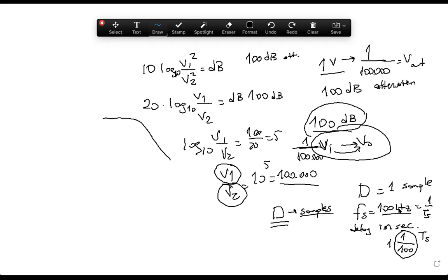That means if I give you 100 Hertz, it means 1 over 100 seconds. One sample. If there is one sample delay, the input will be delayed by 1 over 100. That means 10 millisecond delay. If it is 1000 Hertz, it's going to be 1 millisecond delay. 1 times 1 over 1000. Anlıyoruz değil mi arkadaşlar burayı?